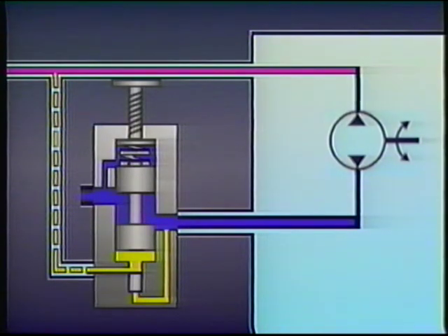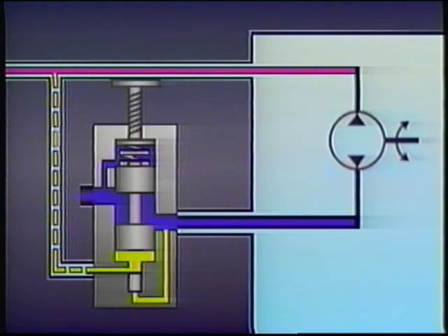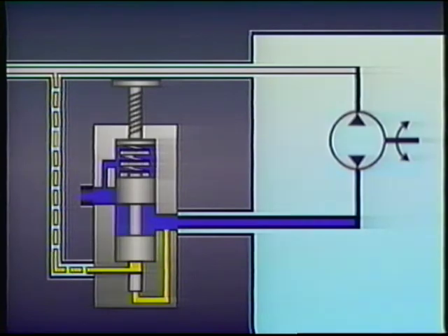As long as pressure at the inlet to the motor is 100 psi or more, the brake valve will remain open. If the load attempts to run away, pressure drops off in the motor inlet line and the valve closes. When that happens, back pressure rises and slows the load down.